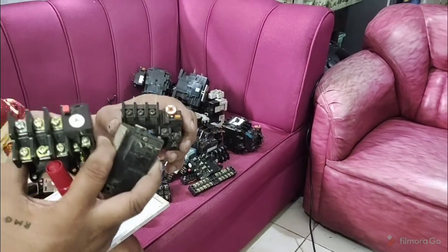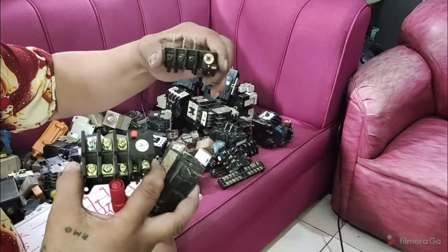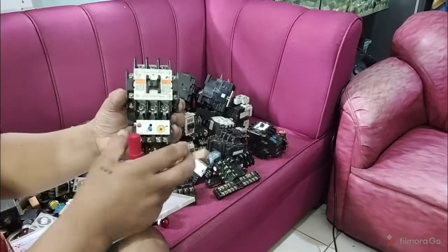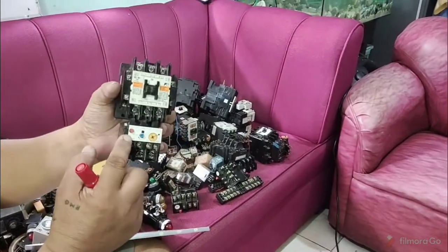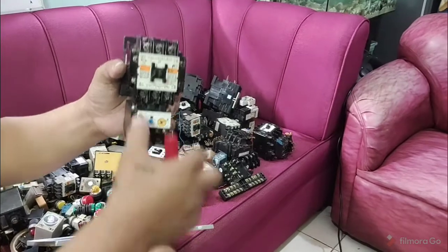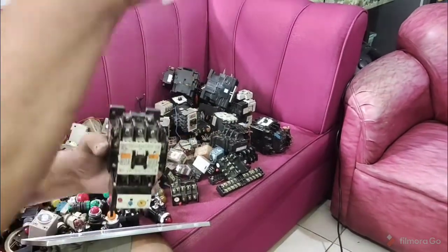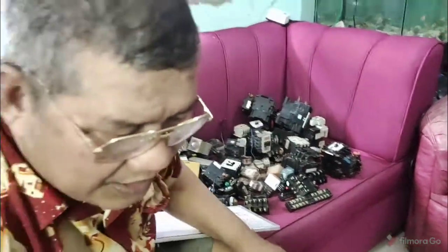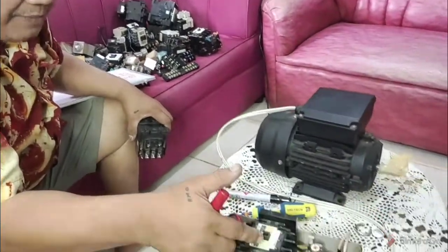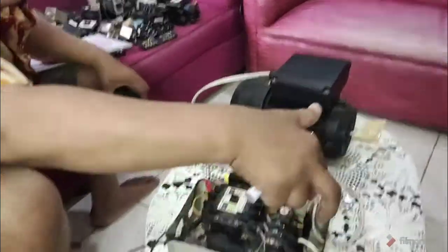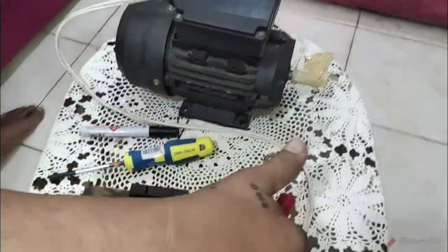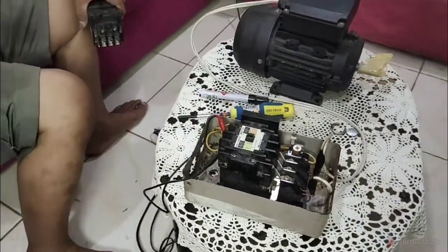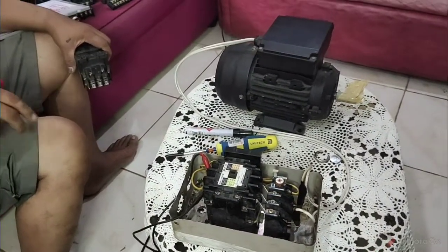And then this is connected in series with your magnetic starter like this. You have your magnetic contactor, you have the overload relay. So this is considered the power circuit. Then you have your circuit breaker, and then below you have the overload relay like this. You have the magnetic contactor, you have the overload relay, then the motor is connected directly to the overload relay, while the magnetic contactor is connected directly to your circuit breaker. Okay? So that is it.